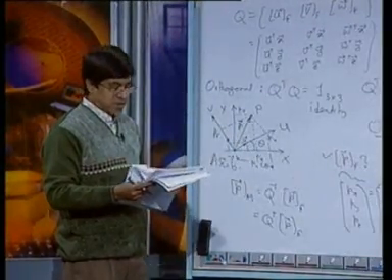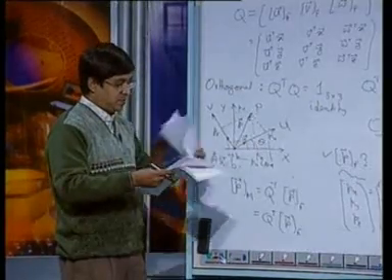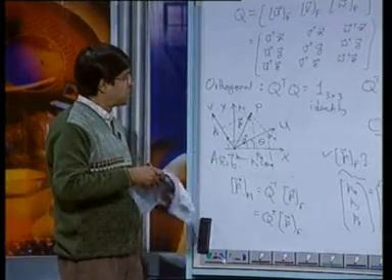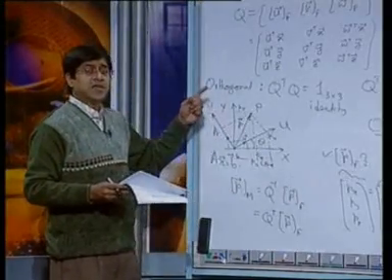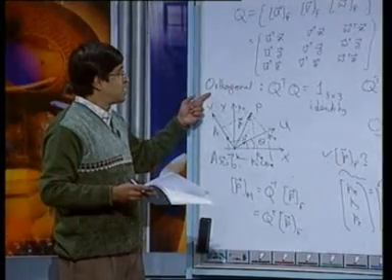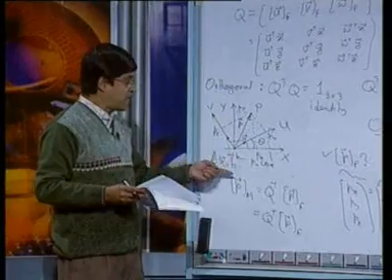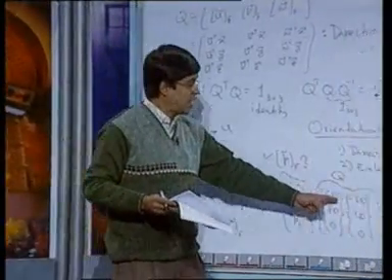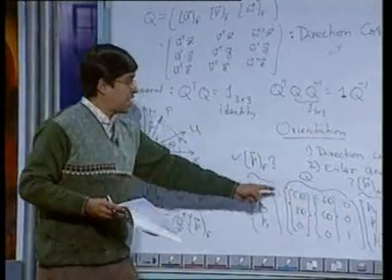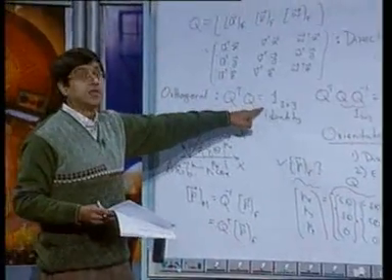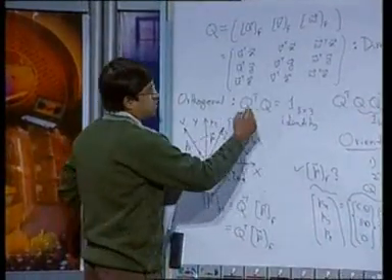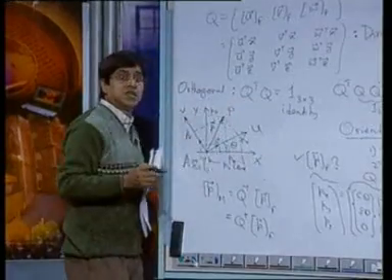the Euler angle representation. Now, one of the disadvantages here is, you see, in case of position, which has 3 degrees of freedom, 3 coordinates were sufficient, but in case of rotations we need 9 coordinates or 9 elements, but all of them are not independent, which means the 9 elements must satisfy this equation. And if you break it, then you will see there will be 6 constraint equations.